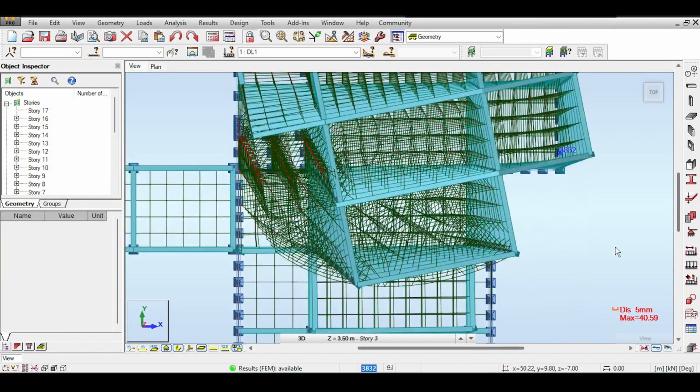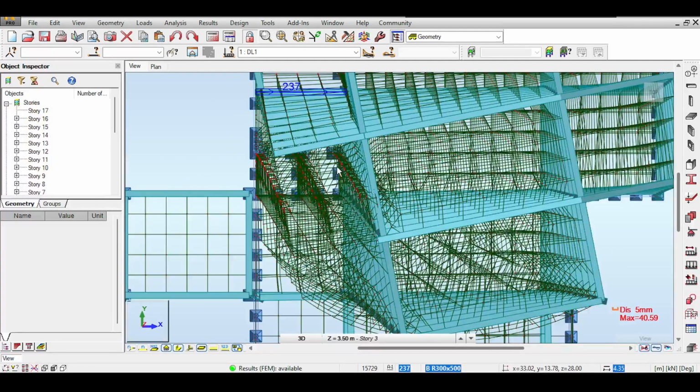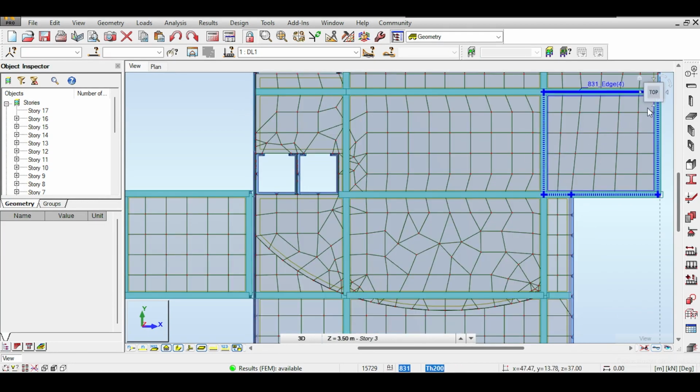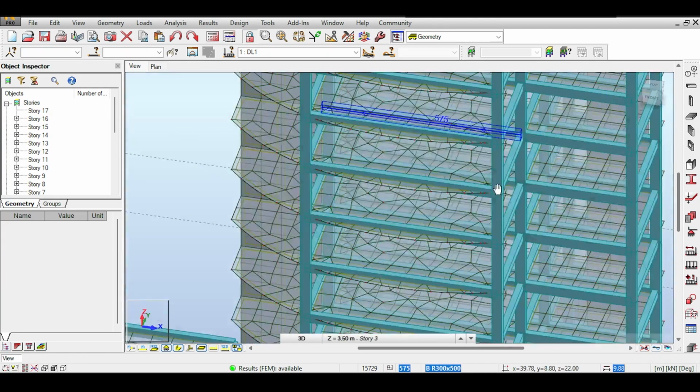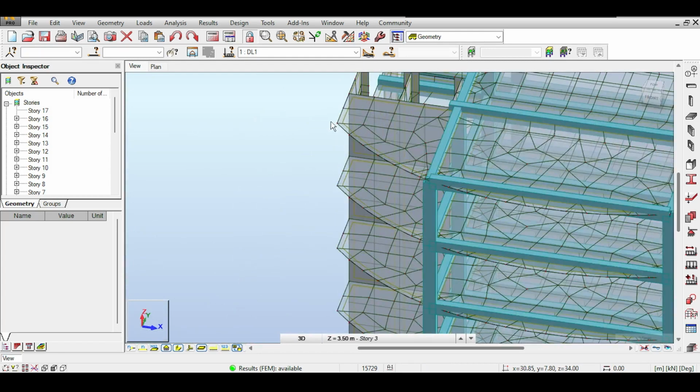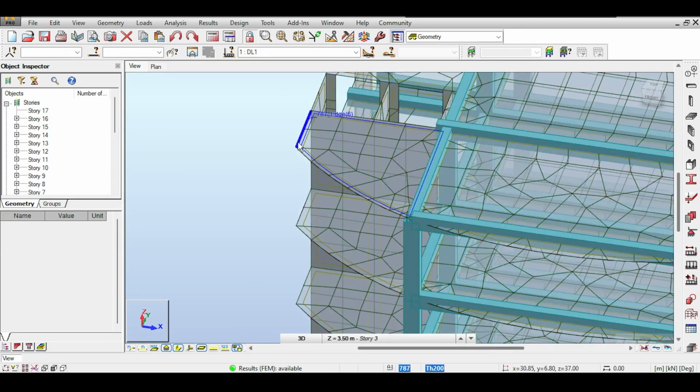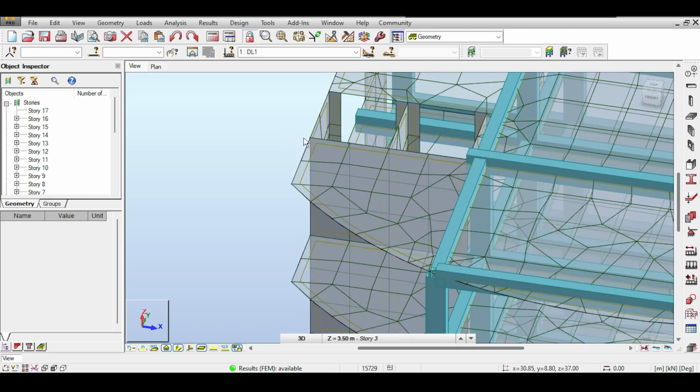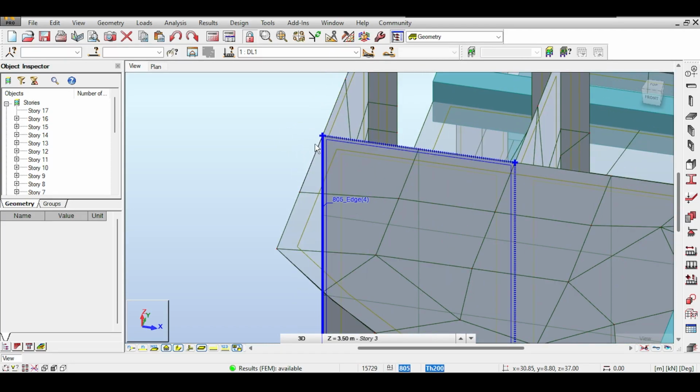So what I'm doing, first of all, to see the progress and to understand what the problem is, I will remove the deflection shape and select basically the nodes. For example, this node. Now this is actually a balcony, so it's already not stiff. So let me just select a point that I know is really stiff. And the point I'm selecting is the shear wall. If you stop on the shear wall, this is thickness 200. That's a little bit too low for a shear wall. I might need to make it thickness 250.